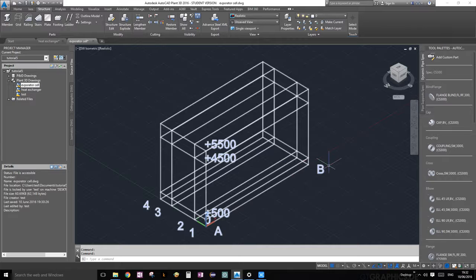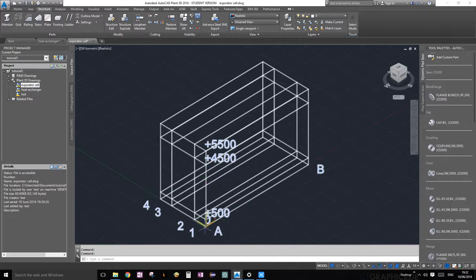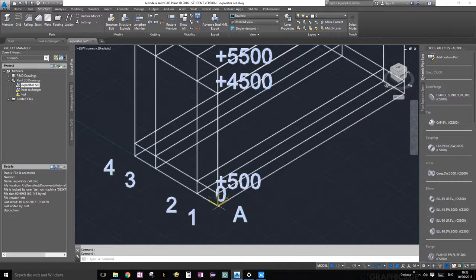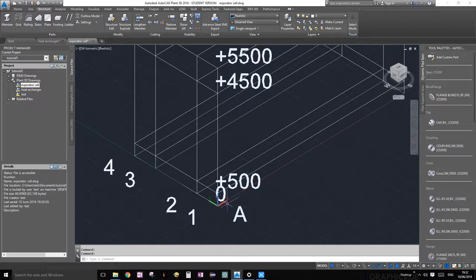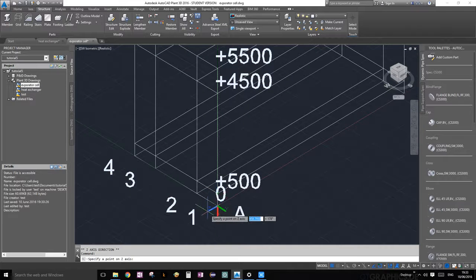Okay, so let's get started. First thing we're going to do is we're going to add our first piece of structural plate here, which is going to be on this little face here. To do that, remember, you can only draw on the x and y plane, so we need to move our z axis, either this way where the x is right now, or the opposite way of x. So just go ahead and click on your coordinate indicator and drag it just like so.